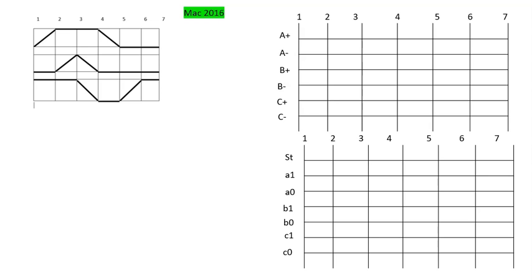So we have this motion diagram with 3 cylinders. Let's start with the label. At time 1 we have A plus, and then we have B plus, B minus and C minus together at time 3, and then we have A minus and C plus. So we have the sequence. And remember that B minus and C minus must be written as upper and lower, alright?